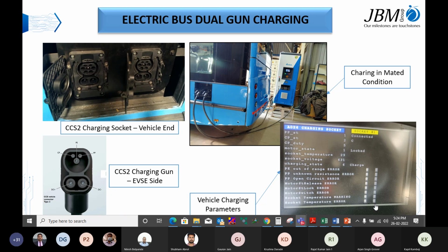One query, sir. The word cell balancing. During charging, does cell balancing take place, sir? Cell balancing takes place after reaching the limits. When we reach almost 90 to 95 percent of SOC, the cell balancing will start in CV mode, constant voltage mode, because the battery has reached the voltage that is required. Then it will remain at constant voltage and start giving the current that is required for cell balancing.